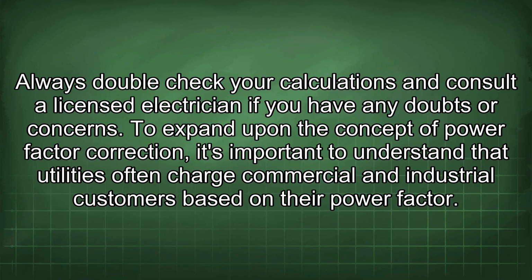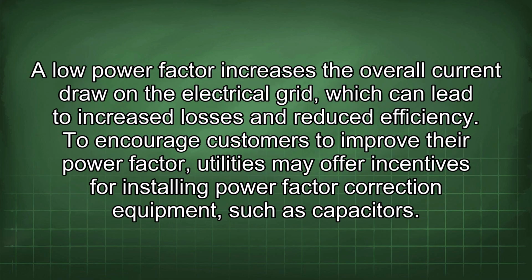To expand upon the concept of power factor correction, it's important to understand that utilities often charge commercial and industrial customers based on their power factor. A low power factor increases the overall current draw on the electrical grid, which can lead to increased losses and reduced efficiency. To encourage customers to improve their power factor, utilities may offer incentives for installing power factor correction equipment,